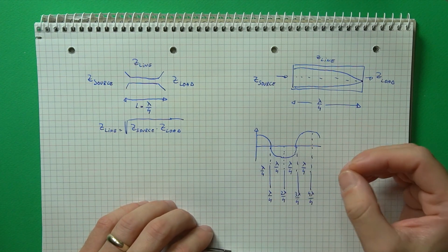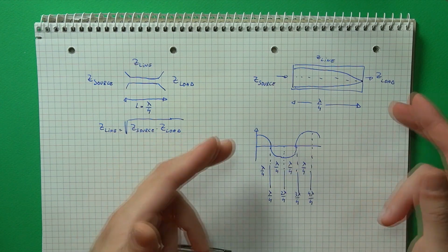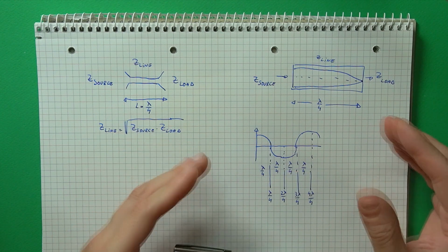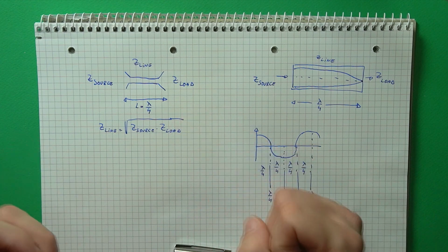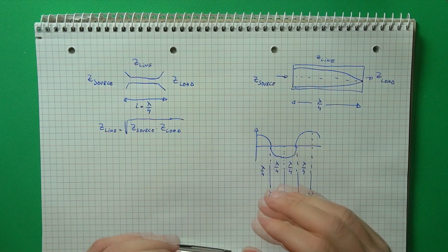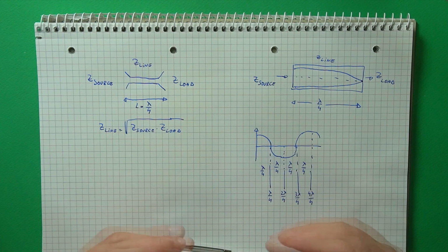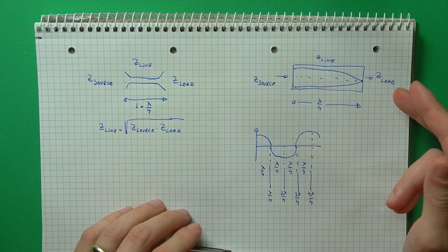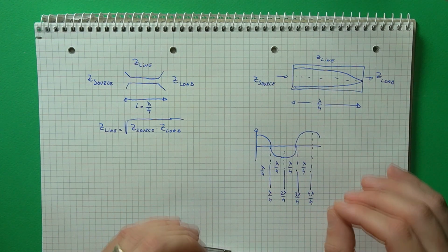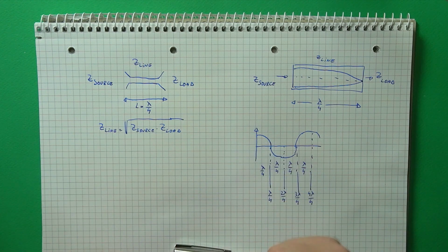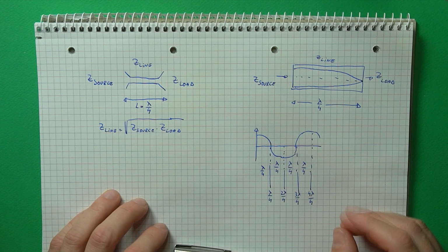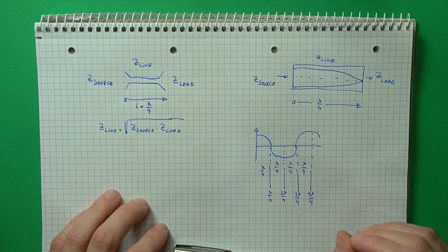Based on this phase inversion and the reflection coefficients at the ends of the line, the final impedance equation is determined. Impedance transformation with transmission lines, to a certain extent at least, will occur with any line length and with any type of impedance. But the nice simple formula only works with quarter wavelengths and real impedances. So the circuit should work quite easily, right? Let's try this out in the simulator now.